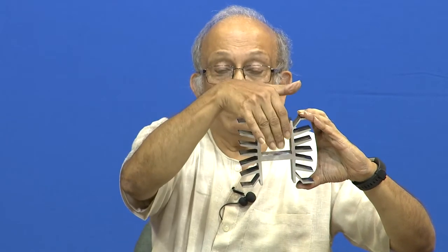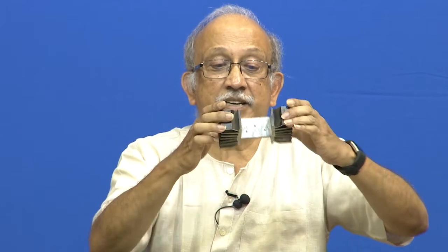You can mount power electronic components, and further if you want, you can create manifolds such that the air from there comes here. Not all the semiconductors have a base, and they can all be mounted here. But imagine you have other things like a toroid, which, if used as a transformer or a simple inductor, will heat up.